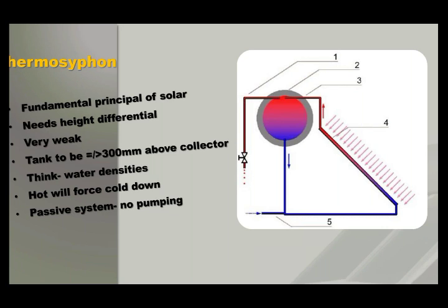There was something else I wanted to say. Oh yes, just because we know about shut-off valves and where the shut-off valves are required, and we'll get to this later, so don't worry too much about it. But shut-off valves are required between panel and tank on both the flow and the return lines.